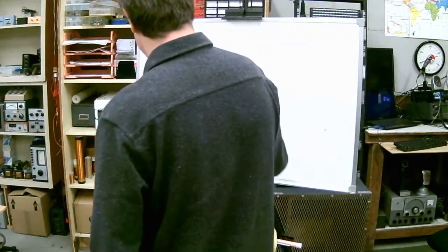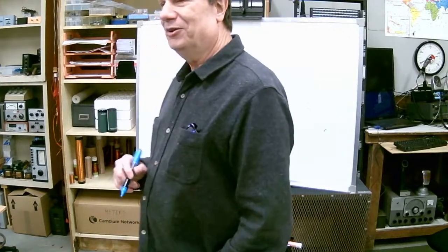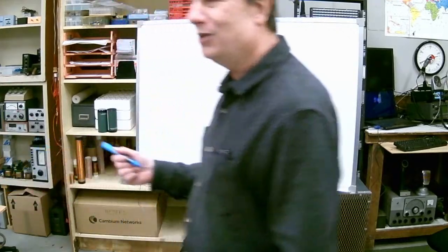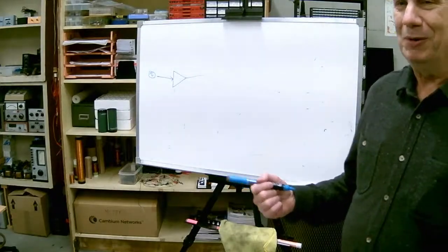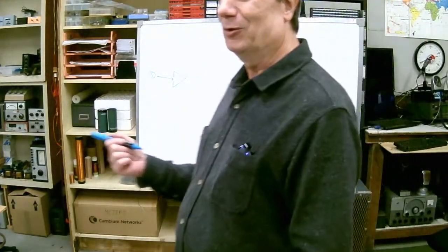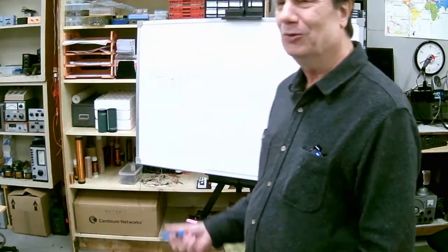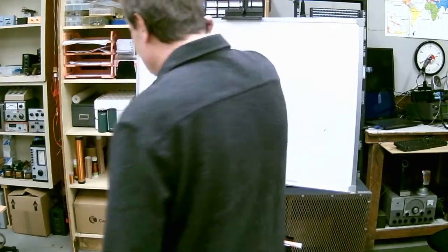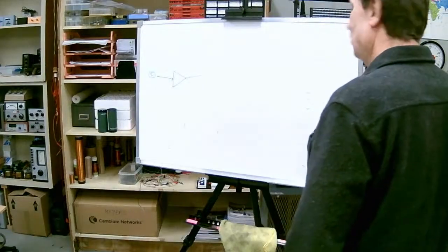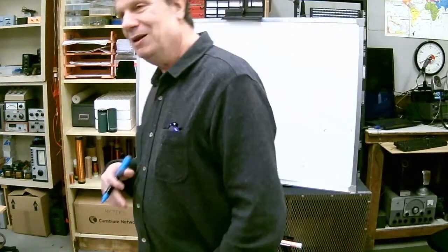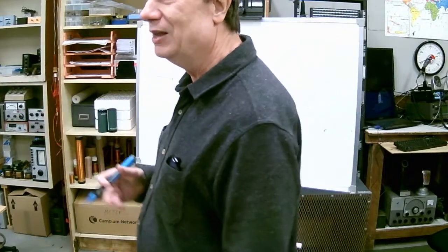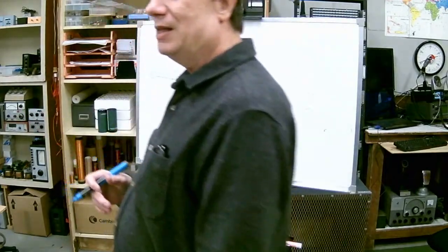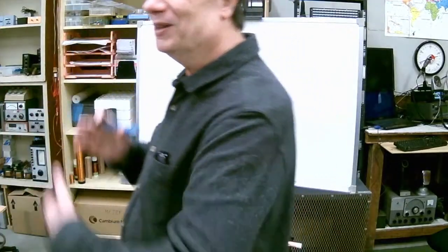So we can do that right in our antenna in a car radio, since we have a very high Q antenna to start with. We've already got quite a bit of selectivity happening just by virtue of the fact the antenna is so small and the Q is so high. But let's say we had a full-size antenna. For example, in the shortwave stuff I do here, I'm usually using antennas that are pretty close to resonant long antennas, with a bit of intercept area.